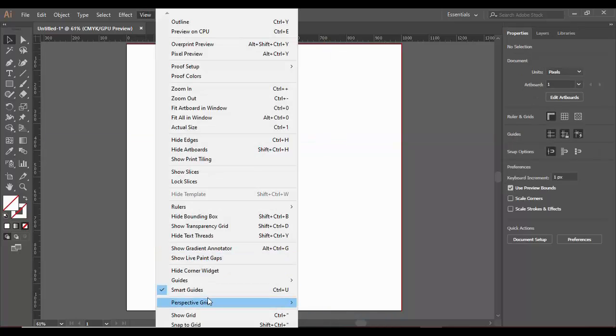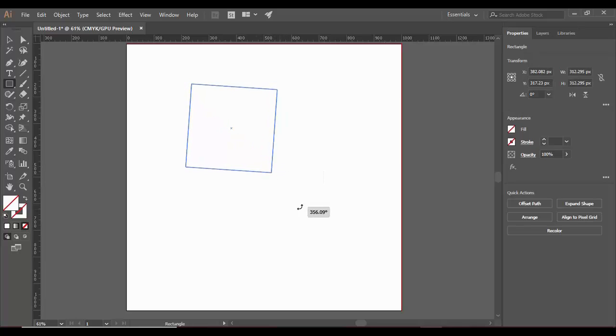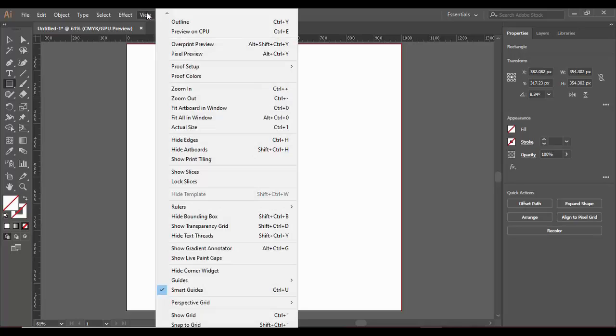Alright. And this smart guides option that is turned on is used to tell you the distance between two things. Like if I draw this rectangle, you can see that this pink line that is scaling on its diagonal is a kind of smart guide. Now if I just leave it here and try and draw another rectangle from here, you can see another line that is connecting the center of this rectangle. It is also a result of a smart guide.